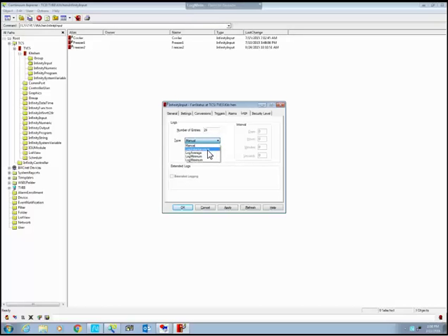You will choose either an instantaneous or an average. I usually use the average. What that does, it looks at over that 1 hour period, which is what we're going to choose here in a second, what is the average over that period? If you choose instantaneous, it's going to give you the value, what it is right at that point, no matter what it was any other time during that hour. Okay, but we're going to do an average. And we want this to be at 1 hour intervals.